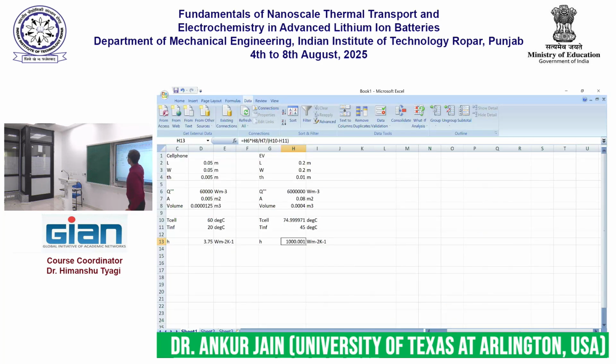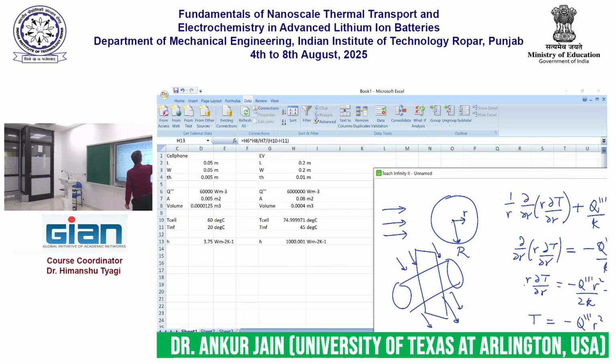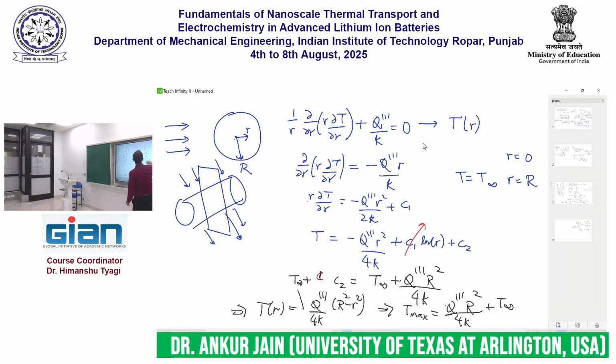Yeah, so this is the reason why I want to have small size cells. And sorry, I was also doing some work here related to cylindrical cells. And yeah, this is where it comes from. The radius must be as small as possible. If I increase the radius, the temperature will go up non-linearly. And of course, if I increase the heat generation rate, then that will also go up.